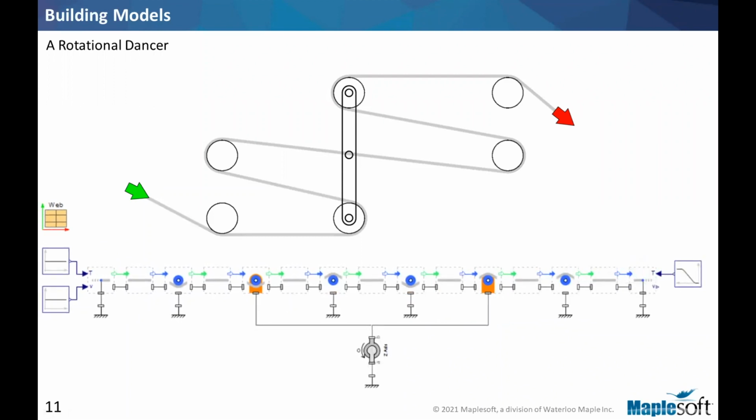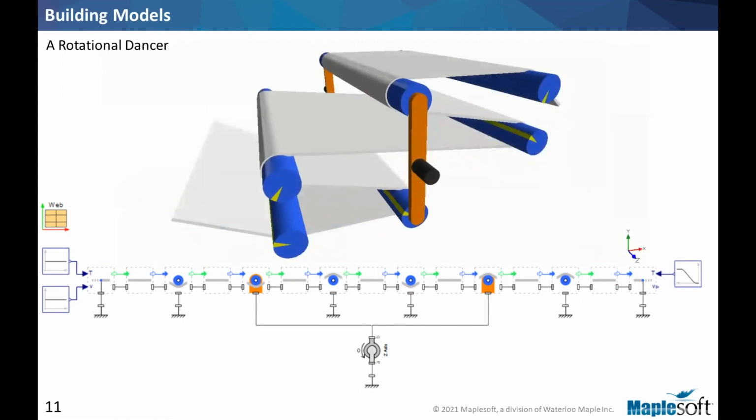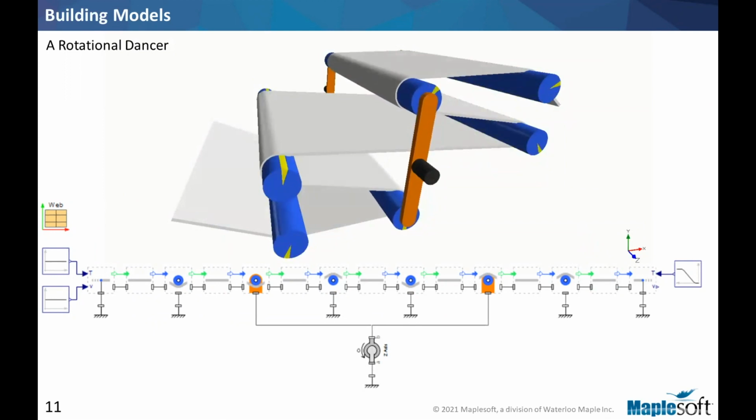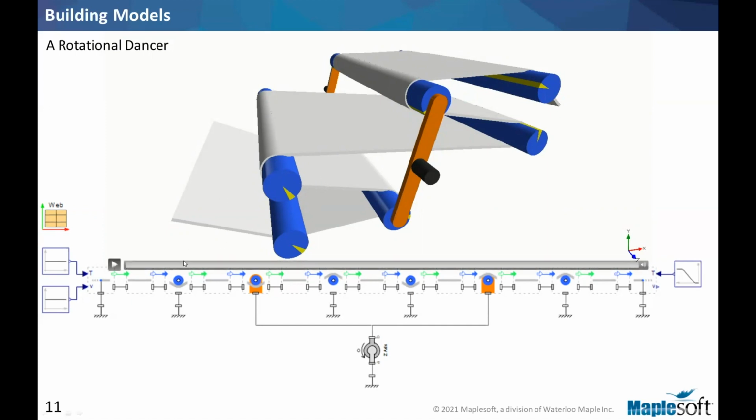And so we can add these 2, figure out the going on top or going on bottom, and by putting the right dimensions for the diameter of the rollers, and even inside diameter if you want to have lower inertia, and the position, we can complete the model and go about the design process that we originally intended. So I included this worked out example to give you a sense of how a model comes together from a block diagram